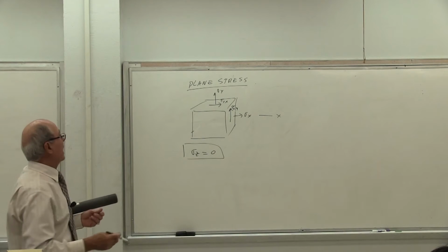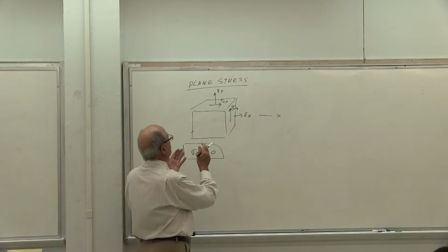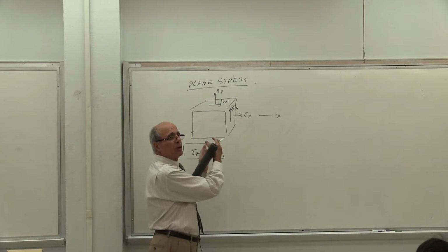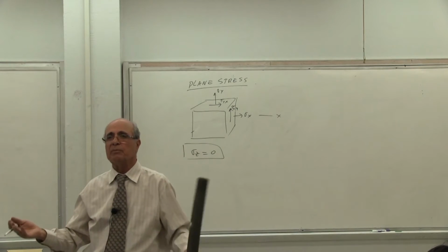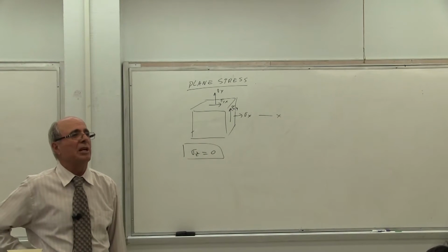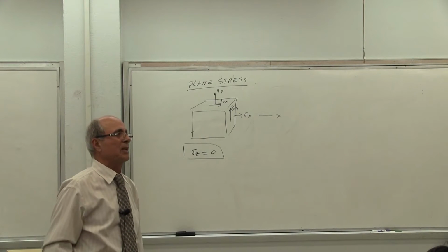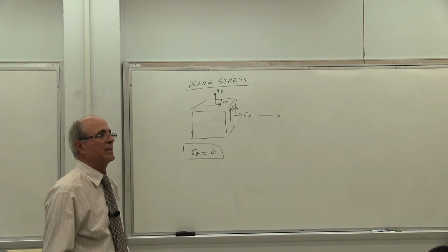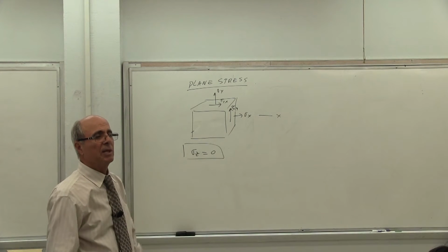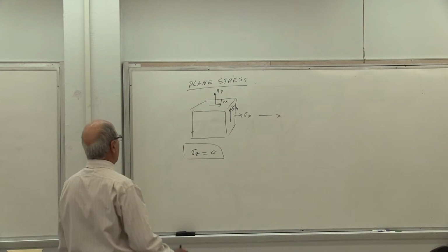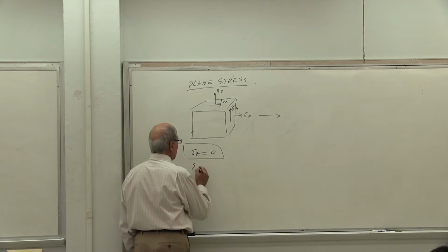And as a result, this is why we don't show it as a cube. Many times we show it as a square. You have done it. 99% of the time you show that as a square, because it's plane stress. Everybody understands, the depth doesn't matter, or we are on the surface as you see it. This surface, that's it. Correct or not? However, what happened to epsilon z?